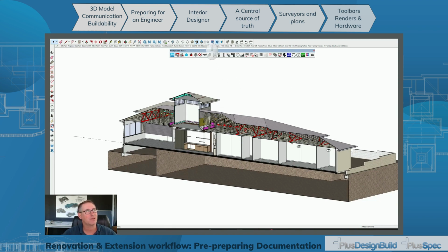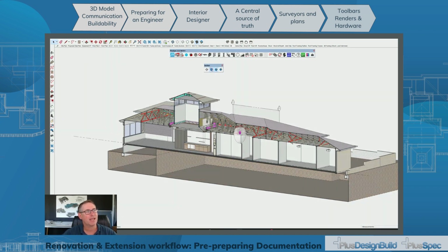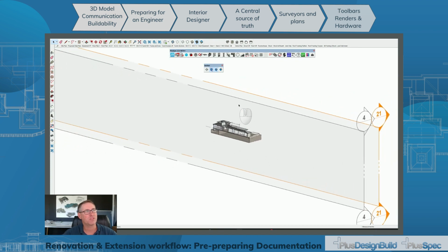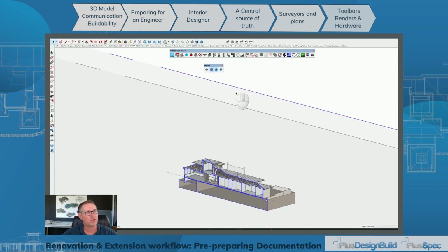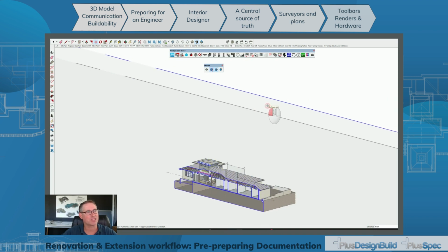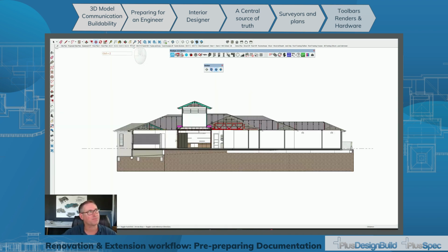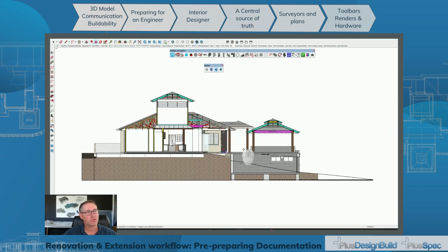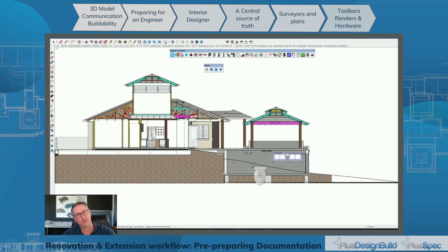And if you actually, you'll notice here that I have my sections tool on, and we'll go through these in a minute. If I click here, it highlighted the section, and if I wanted to move the section, I choose the orange one and I move it to wherever I want it to be inside of the model. So I'll quickly just move this now. Right, and you'll notice that it's sectioning where I want it to be. So once I'm happy with that location, I just basically go right click update scene. Right, I'm going to Control Z it because I actually want that where it is. And that's how I'm getting these section cuts through the model. Section through the turret, and for me, guys, I come from carpentry background.